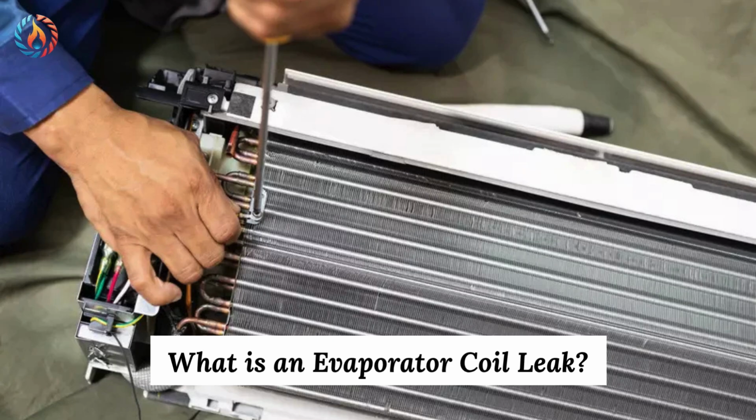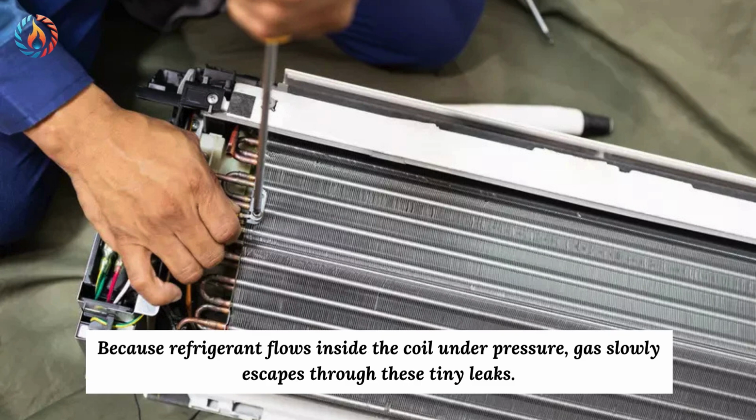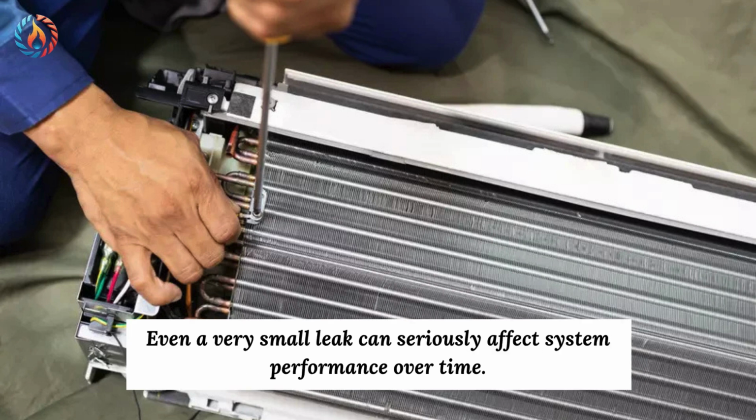What is an evaporator coil leak? An evaporator coil leak happens when small holes or cracks develop in the coil tubing. Because refrigerant flows inside the coil under pressure, gas slowly escapes through these tiny leaks. As refrigerant decreases, the AC loses cooling performance and starts developing problems. Even a very small leak can seriously affect system performance over time.